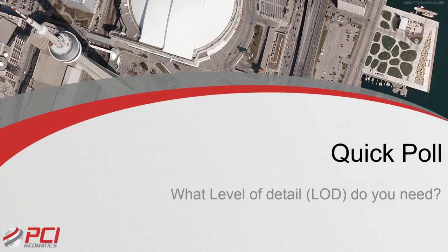On the CityEngine side, if you wanted to obtain the Z values, when you align those geometries to the terrain, it gives them an actual z-value that it leverages, and then you start your extrusions from there based on your GIS data attributes. But in the 3D CIM, or the 3D city data model that I mentioned earlier, there is a geoprocessing tool that will allow you to set your heights for all the building footprints, the base height, directly from your imagery as well. So there's a couple of approaches to making that happen.